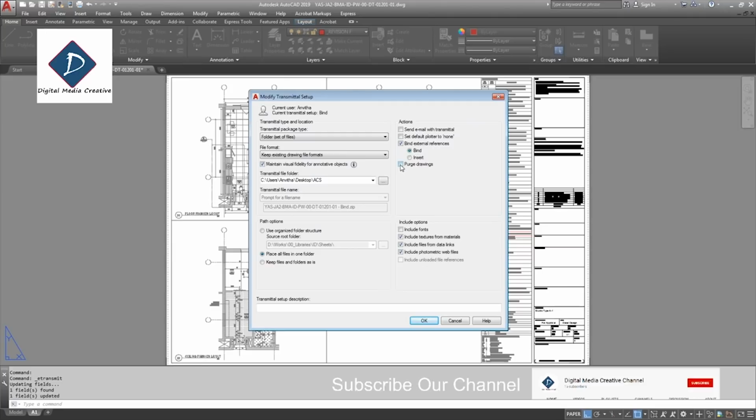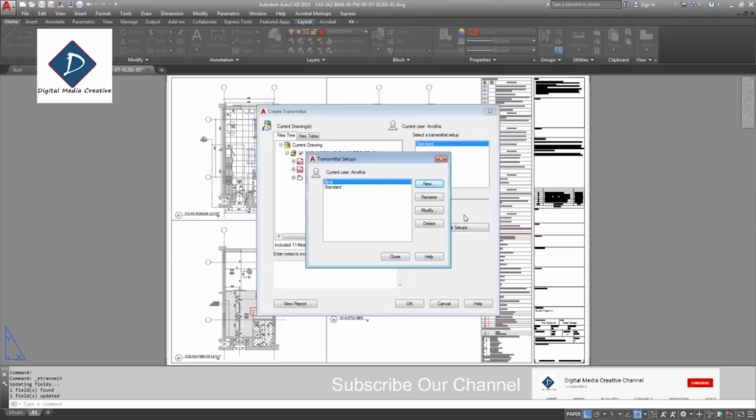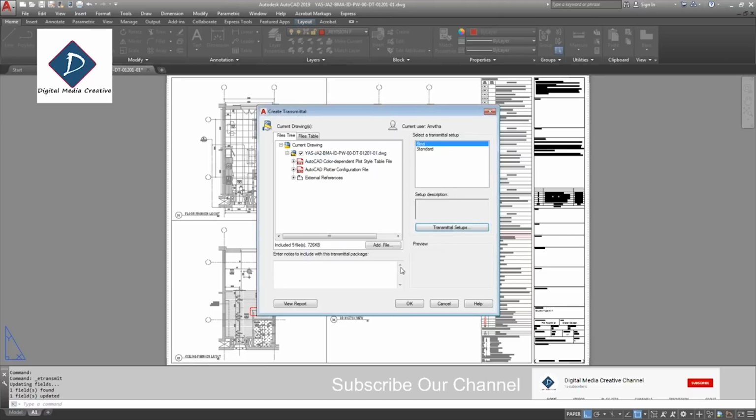Sometimes we'll click purge, but it will take a little bit more time. If you have more files, don't purge it. Click OK, then just close. So you can see here which one you want to select. Okay, so I'm going to click bind.